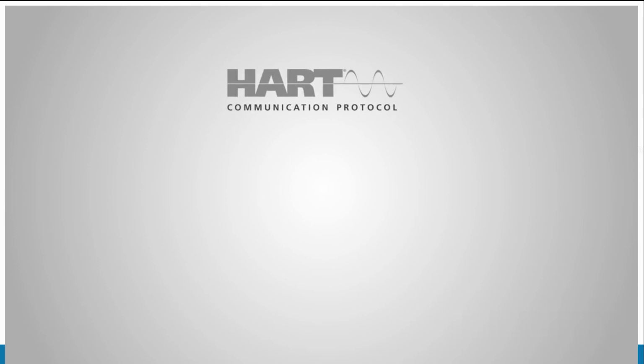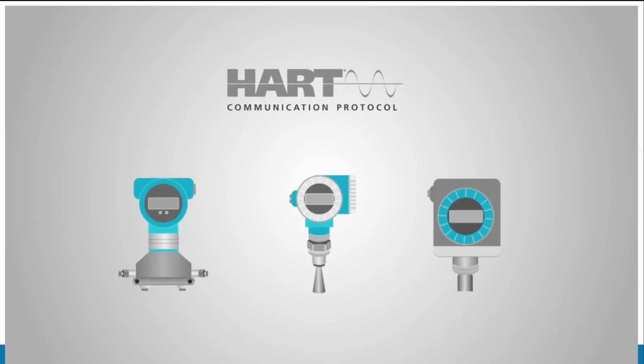The Hart protocol is governed by a vendor-independent association, the Hart Communication Foundation, so Hart sensors from any manufacturer can be interchanged with those of other manufacturers. This makes implementation, maintenance, and troubleshooting very easy. Also, Hart is used extensively for final control devices, such as control valve positioners, with the same benefits and diagnostic capabilities.